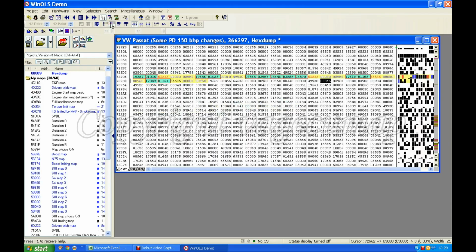Now just go back to 16-bit so that we're looking at what we were looking at originally. Let's assume that we are now correct. Obviously it'd be very simple to find out, wouldn't it? Because I load this file into my car, which already had EGR errors, or didn't. But I load it into my car, let's say, and I unplug a connection to the EGR actuator, which will throw up instantly faults about the fact that the line is unplugged. Or maybe I disconnect the vacuum pipe and plug it, or maybe I leave everything alone but I put a blanking plate in the EGR.